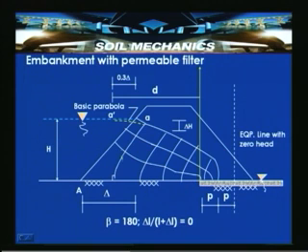So here the number of flow channels is channel 1, channel 2 and channel 3, so 3 flow channels, and then the equipotential drops. By estimating the number of flow channels and the number of equipotential drops, one can determine the quantity of seepage with the rock toe filter.